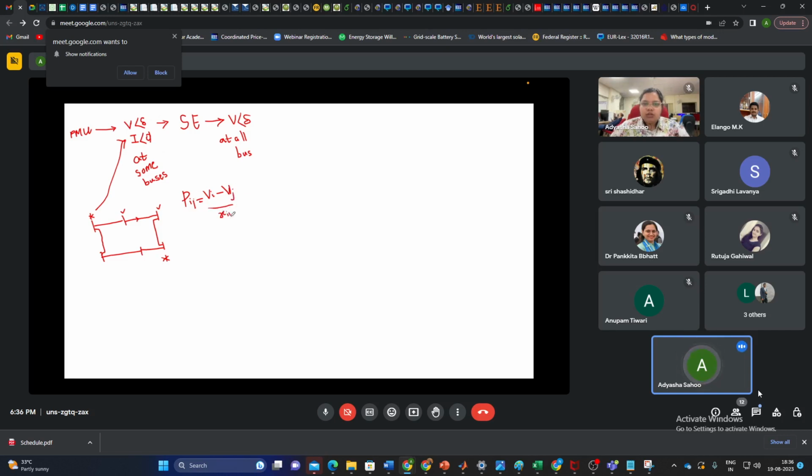So once we know V and I, we can calculate the power flowing, Pij, Qij, then you have Q generated also, that information obviously the system operator is having. Q load also, if there is some changes, so you can calculate the Q injected also. Q injected and P injected, that is Q generated minus Q demand.